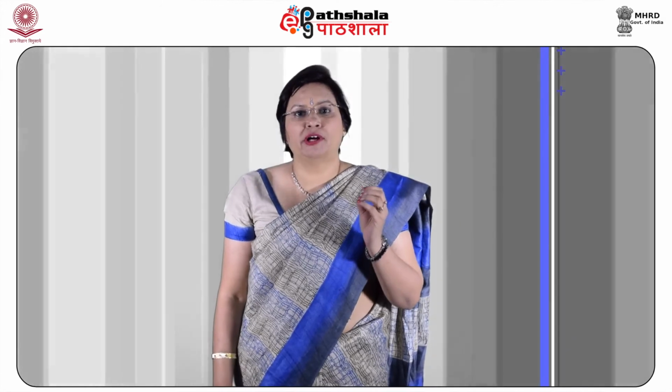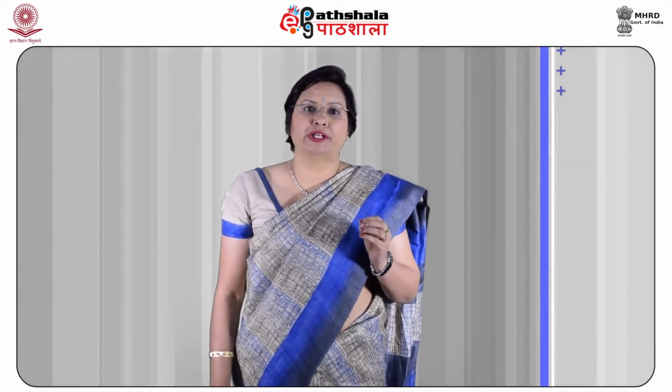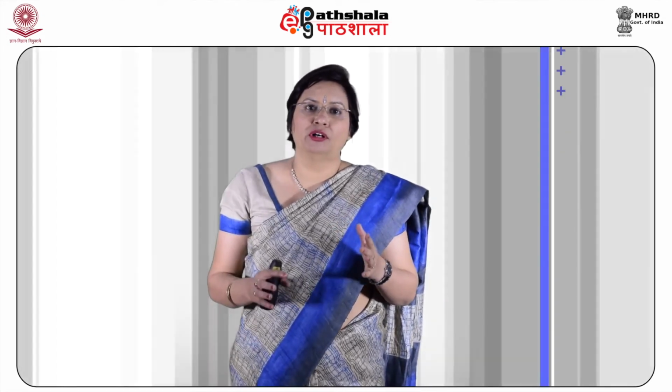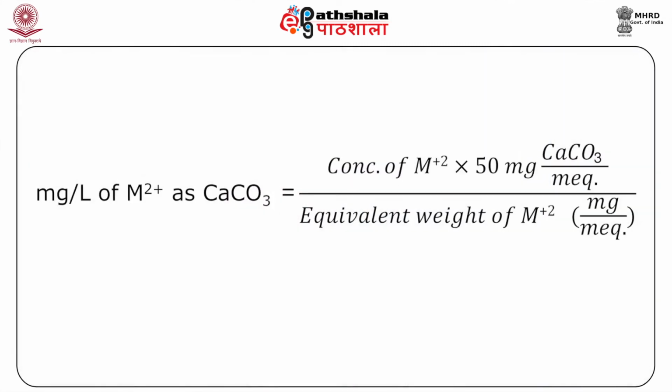For calculation of hardness and alkalinity, the equivalent weight of calcium carbonate is considered, which is 50 grams per equivalent or 50 milligrams per milli equivalent. For calcium ion itself, the equivalent weight is 40 divided by 2, that is 20 milligrams per milli equivalent. And if we talk about magnesium ion, the equivalent weight will be obviously 24 divided by 2, that is 12 milligrams per milli equivalent.